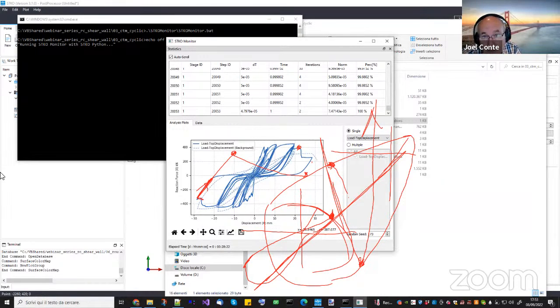Yeah. So there are drawbacks, as we said, there are nice things and bad things from both points, because with a three-dimensional model, you are able to have the biaxial increase in compression, the triaxial behavior, but you have also drawbacks. You cannot model things like this kind of unloading, reloading function. So each model has advantages and disadvantages. This is the point. No model is completely perfect.